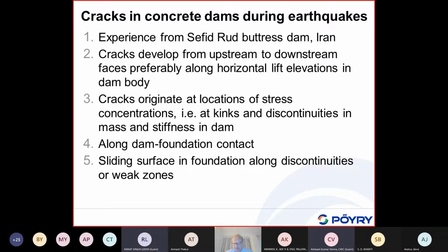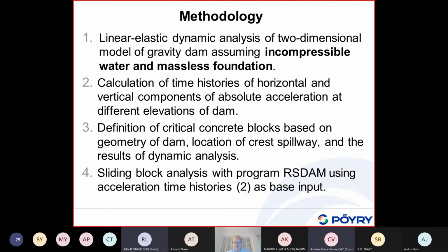It is quite tricky to find fine clay layers, and it was there in a sandstone, siltstone, mudstone formation, where such clay layers were found. At first they were not found, but later on, with some more sophisticated equipment, they were found, and it led to a change of dam type from an arch gravity dam to a gravity dam, actually. So some small layers can have big consequences.